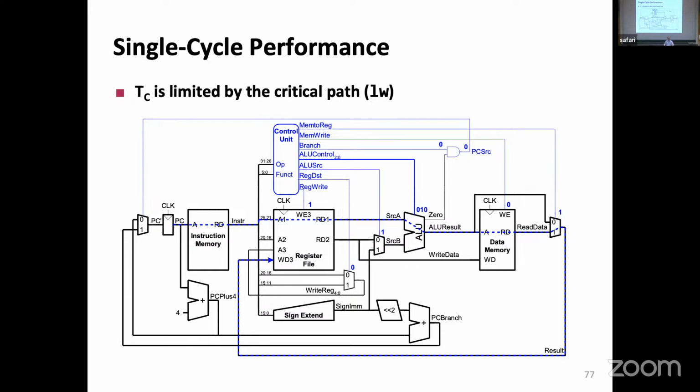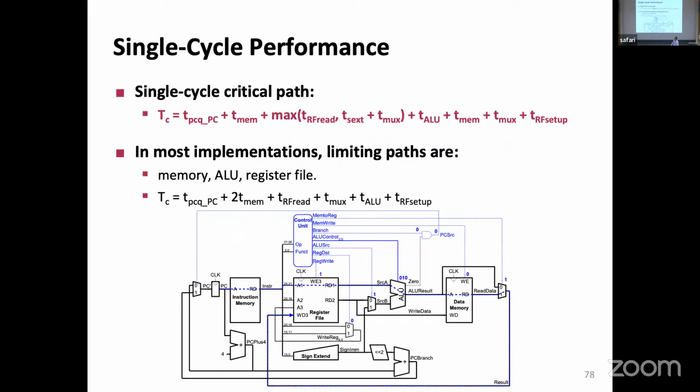Now, the annoying things we talked about timing will come in here because, well, this is a register. The clock comes. There will be a propagation delay. This is a combination logic, propagation delay, combination logic, propagation delay, combination logic, propagation delay. I'm tired. Propagation delay, propagation delay. And I'm about to write in here a setup time to be able to do this. Now, this just writes these things.